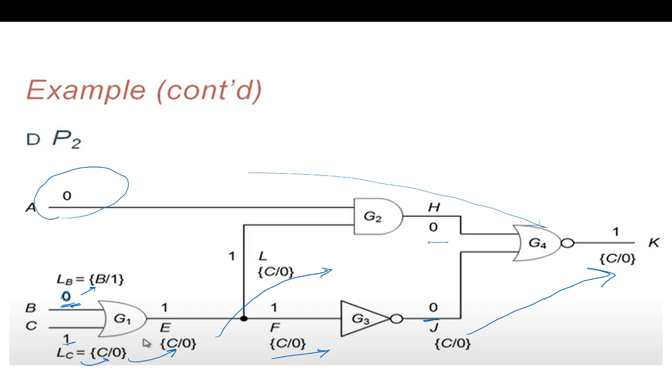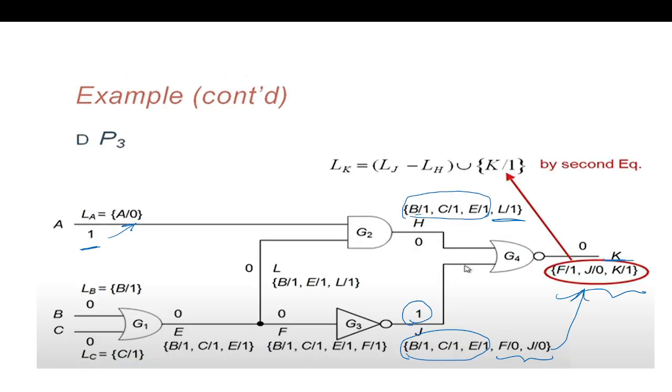So this was the first example. In this example, this part was having a controlling and non-controlling value. These are the list of faults which can be detected by the controlling portion also. We previously said that the controlling portion will propagate. But this is also present in a non-controlling, which will be masked here anyway. So this will be masked. Only these two will be propagated to the output.